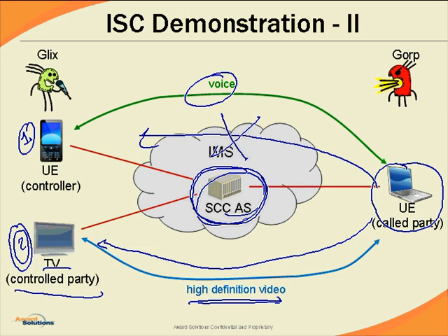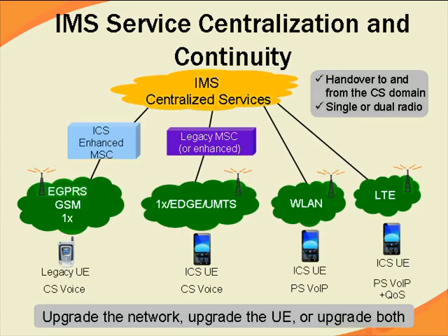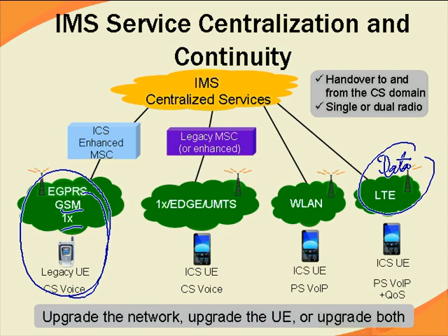So in the cellular world, we can have voice, for example, on legacy circuit switch technology, could be GSM 1X, and high-speed data, we can use LTE. So in that case, we have even possibility of having multiple transceivers. Right? The cost of the device would be higher, but we can use one technology for voice call, another technology for data at the same time.